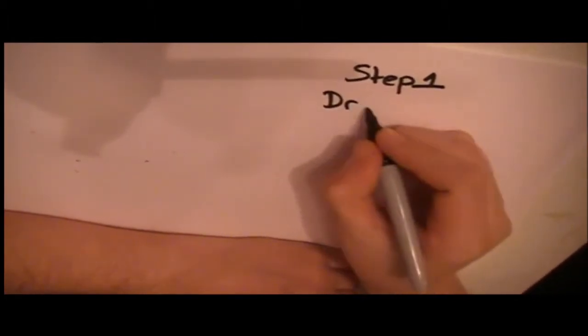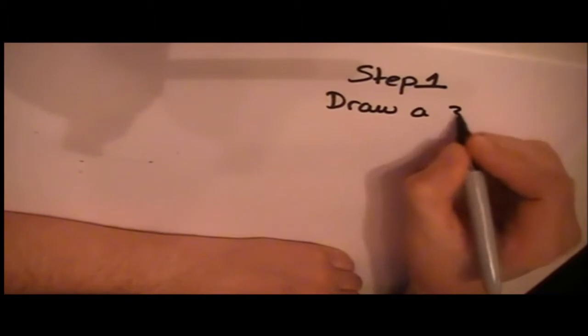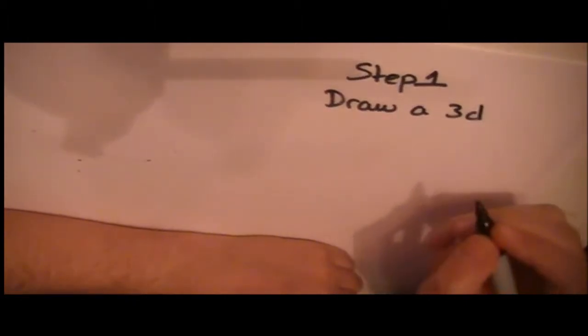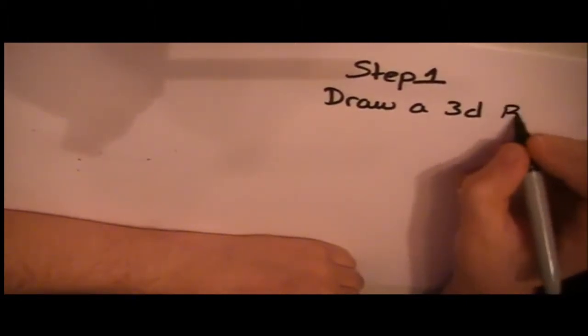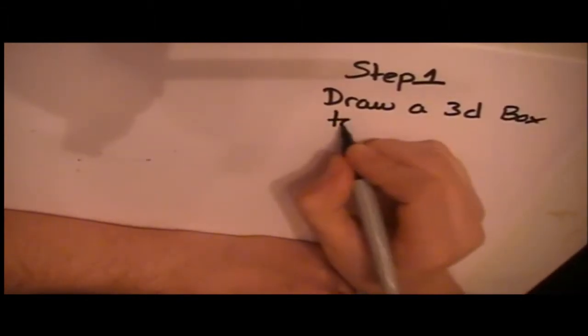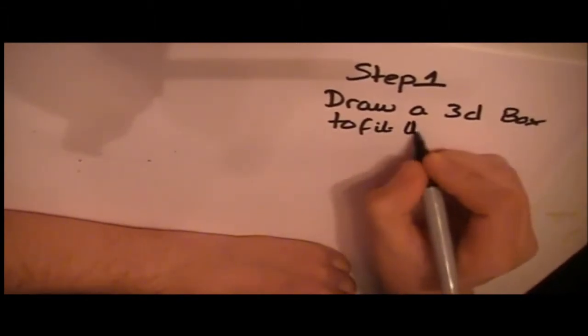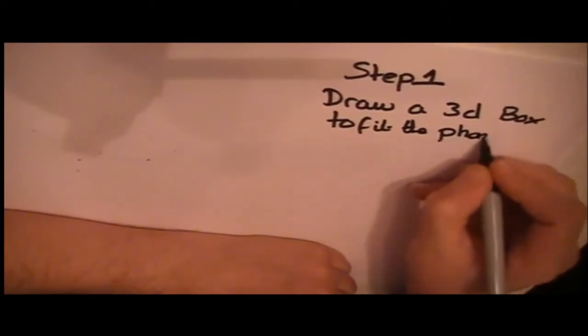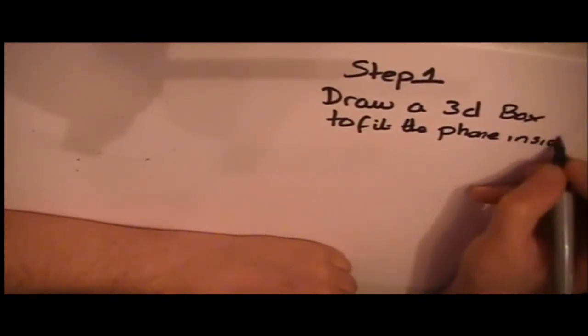First thing we're going to do is draw out a three-dimensional box that you would imagine the phone would fit in. So if you imagine the packaging that the box would go in. We're just going to do it, and this technique is called crating. Now I'm going to do it with a normal propelling lead pencil, freehand, but if you're struggling, just download some isometric grid paper, lay it under your sheet and sketch out the basic shape first with that. It really is that simple, and this will just help you to keep all your proportions correct.